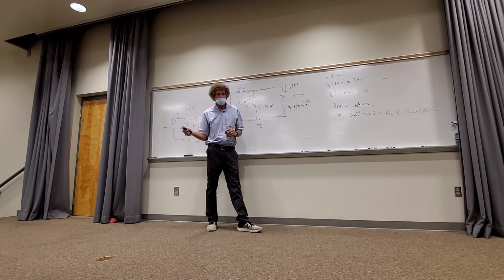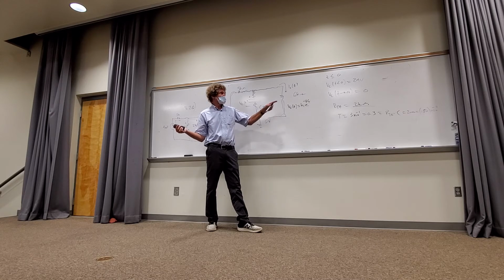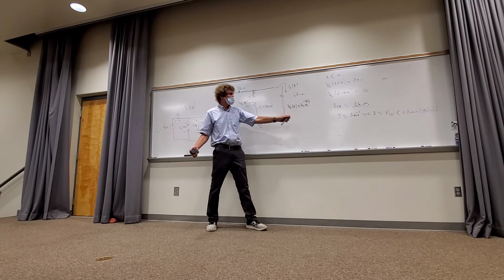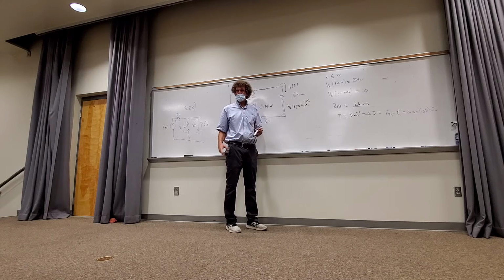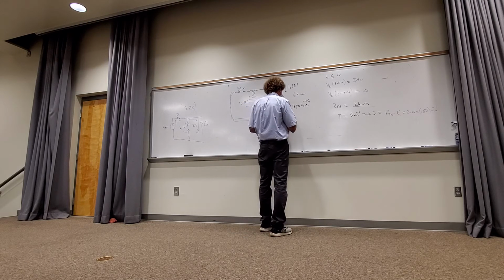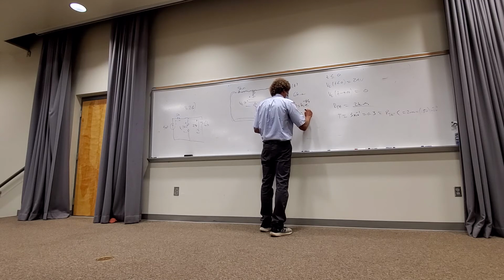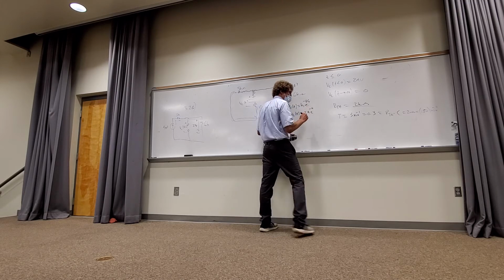How about K1? How do we get it? At this point, it's by inspection just left. It's got to be 24, doesn't it, class? Because that's the voltage at t equals 0, isn't it? When t equals 0, e to the 0 is 1. It's got to be 24. Agree, class? So that means Vc of t is equal to 24 e to the minus t over 0.3.